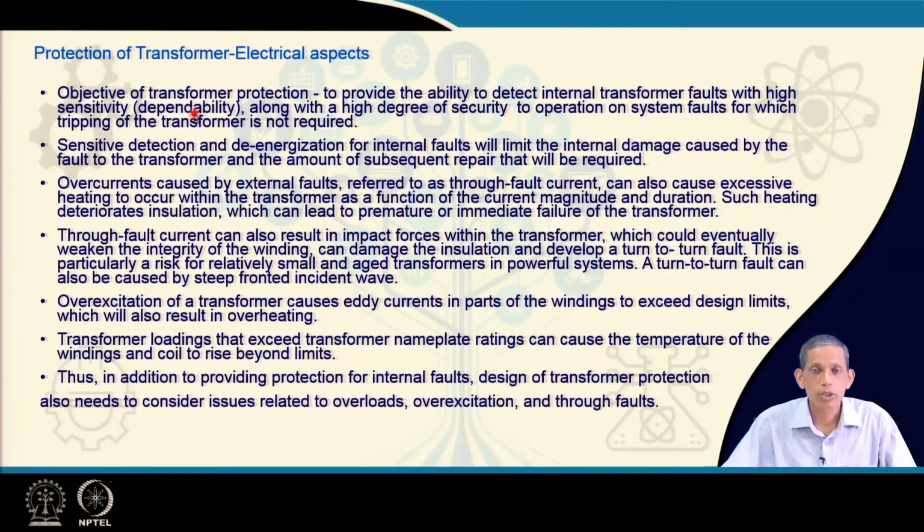The transformer is a critical element in the system from the point of view of reliability of supply, or in terms of economic perspective. Therefore, the fault detector should be very sensitive, and the speed of operation of the relay should be as fast as possible, so that possible damage can be avoided. For any internal faults, that must be considered as fast as possible.